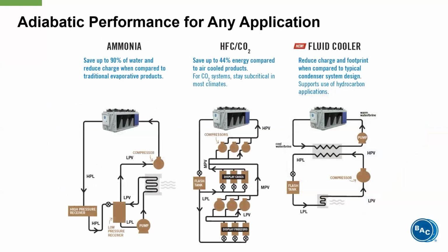When it comes to adiabatic products, they can be applied really for any application. They're available with stainless steel coils for ammonia applications. They're available with high pressure CO2 coils, so we can have direct CO2 condensing or gas cooling. And they're also available with water glycol coils. So we do quite a bit of adiabatic fluid coolers as well.